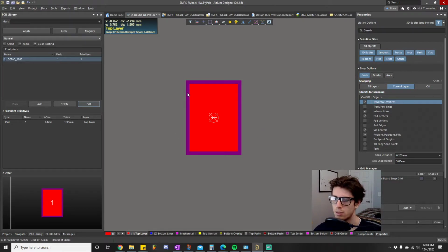We can talk about, and this will probably get more into PCB design rules, how you actually know how big this purple box is supposed to be. That really depends on a few things. It has to do a lot with the manufacturing process. Some manufacturers can get this really tight, because maybe in a perfect world you would say keep this tight, make it 0, right? Make this opening only the size of the actual pad.